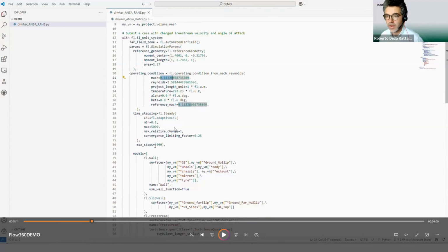You get basically a ramp automatically generated, and the ramp will adapt based on the local flow condition. So you don't actually have to set up anything. The only parameter that you change is 0.25, which is the standard one. If you go lower, it will be more gentle. If you go higher, you get it stronger. But this is the recommended value. That's the only one, and then it will be automatically done.